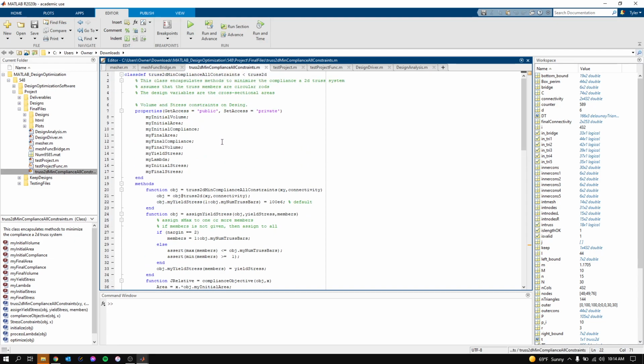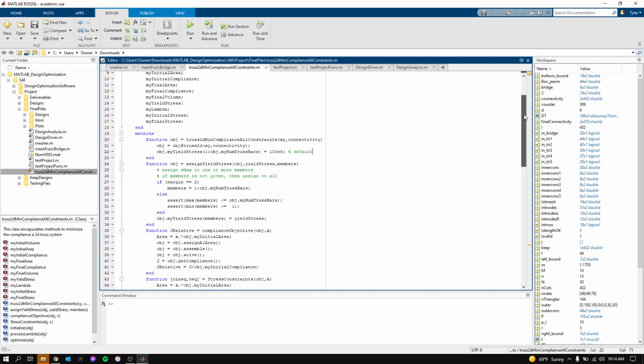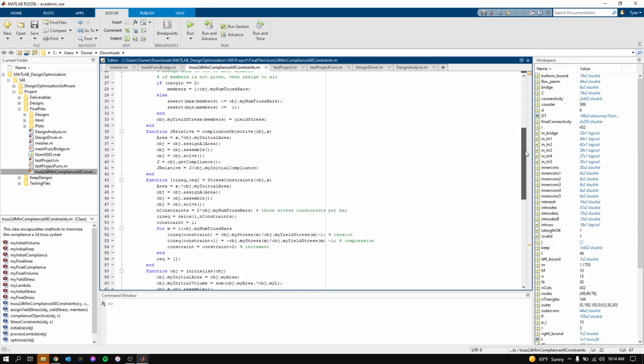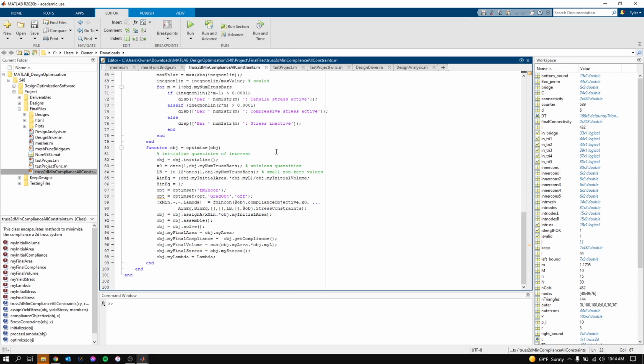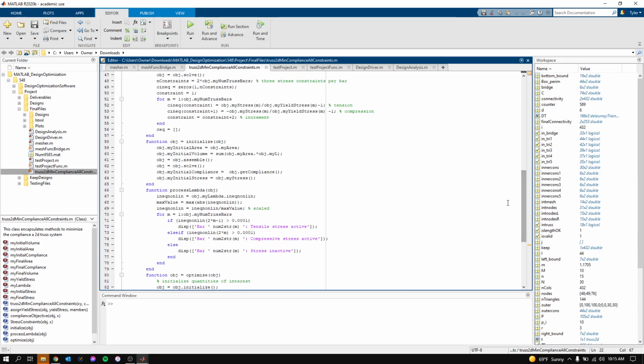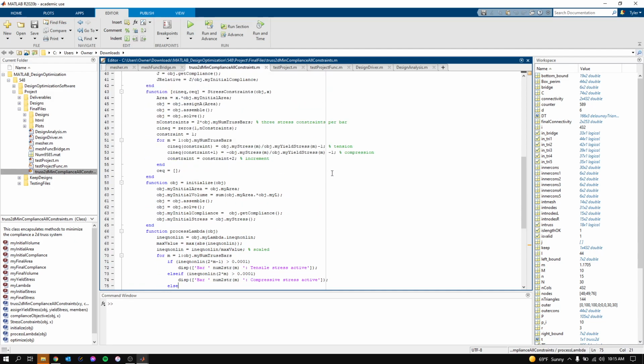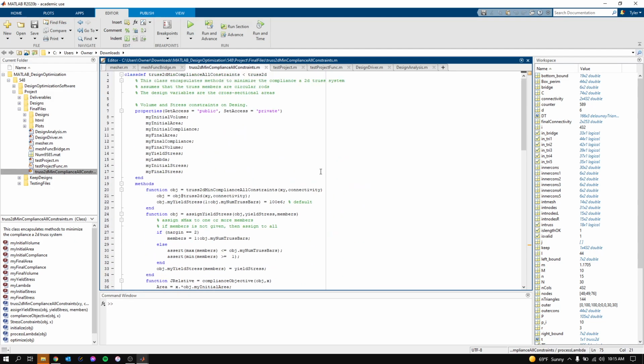this does with your volume constraint, your stress constraint, your volume being the mass, the total material, your Young's modulus, your yield stress of the material here, it will reallocate the material, so it will make certain members thinner and certain members thicker to minimize the deformation, minimize the compliance, increase the stiffness of the bridge design. That's what this does. So this is the optimization algorithm and the mathematical theory for our constraints here. You see we actually have a couple constraints, tensile and compressive for each member. So we have to analyze tension and compression for each member and things like that.